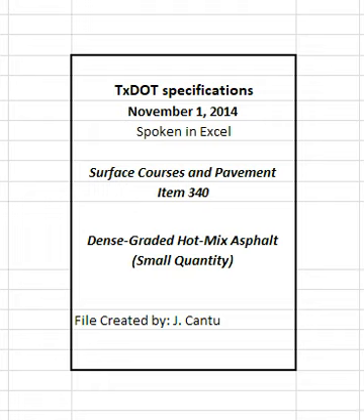Instead of the contractor trimming the cores on site immediately after coring, the engineer and the contractor may mutually agree to have the trimming operations performed at an alternate location such as a field laboratory or other similar location. In such cases, the engineer will take possession of the cores immediately after they are obtained from the roadway and will retain custody of the cores until testing is completed. Either the department or contractor representative may perform trimming of the cores. The engineer will witness all trimming operations in cases where the contractor representative performs the trimming operation.